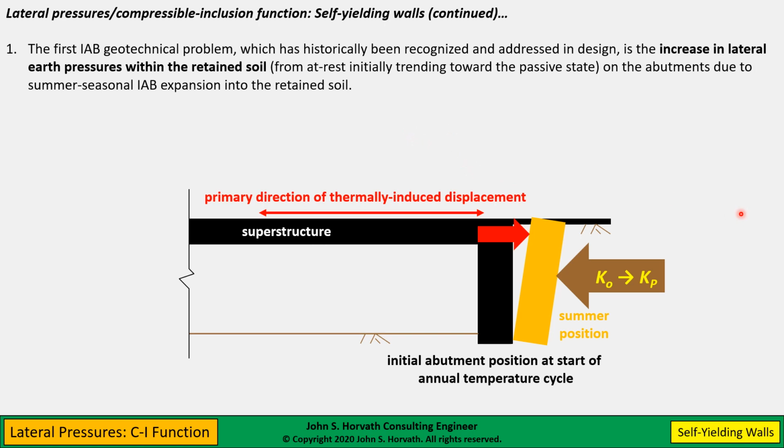And there's been a fair amount of research to analytically and experimentally come up with pressure diagrams to design for this. So this is something that integral abutment bridge designers have known about for decades. This is not a new concern. But traditionally, they simply design the abutment to take this higher earth pressure. What we'll see is there's a better way to do things.